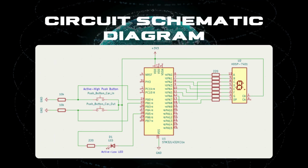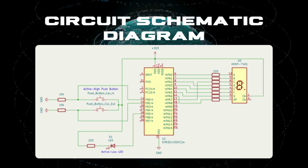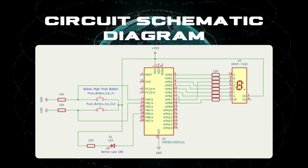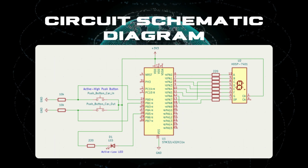For the input button connection, the car in button is wired to PB0 with a 10k ohm pull down resistor to ground and the opposite side to 3.3 volt, whilst the car out button is wired to PB1 with a 10k ohm pull down resistor to ground and the opposite side to 3.3 volt.